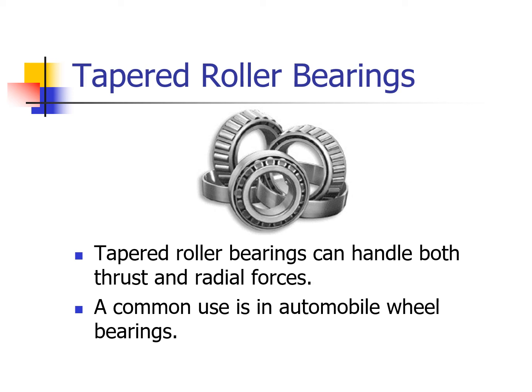So to eliminate that, I have this tapered roller bearing, and if I am pushing out on the big part into the thinner part, there's no way that it could come apart, right? A common use of these bearings is in automobile wheel bearings. They use tapered roller bearings. There's generally two of them, one on each side, one pointed one way, one pointed the other, and that way it can handle the thrust load without the bearing coming apart.